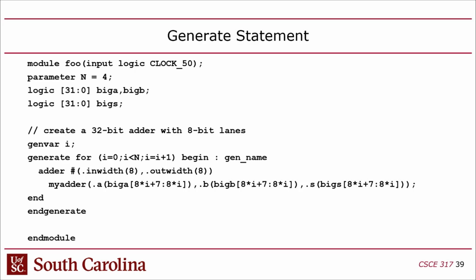Now, why do you need that? The reason you need that is because when you simulate this, it's going to have to create instances, and this is the prefix it's going to use, right? So if you put PWM, this is going to cause it to create PWM0, PWM1, PWM2, and so forth. That's what it'll be called inside the simulator.